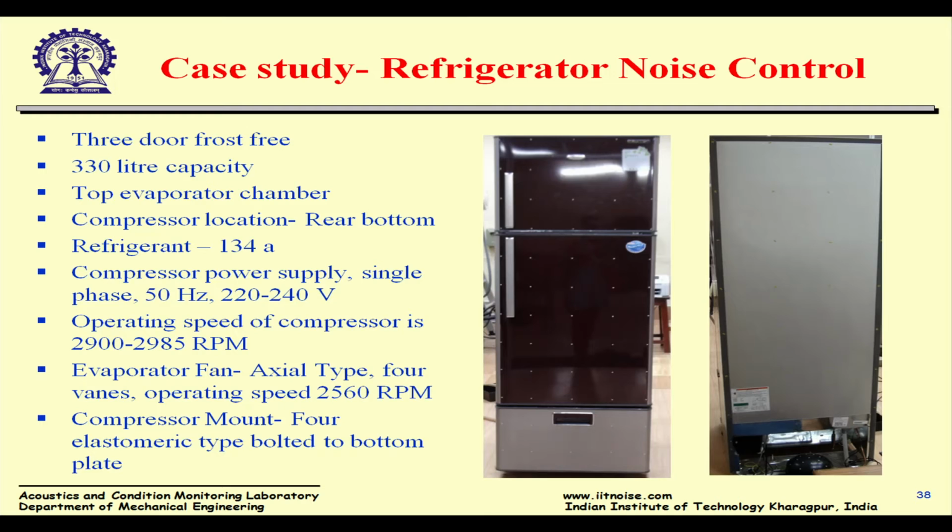Now I'll come to another case study where we'll talk about how the noise control of a refrigerator is done. And by now perhaps you all know, for noise control to be implemented on any machinery, noise source identification, path characterization, property evaluation, and then matching with the right kind of materials developed. Is it structure borne? Is it airborne? If it is airborne, what kind of materials, where to put? And so all this, I will go through some of the results which you have done for this refrigerator.